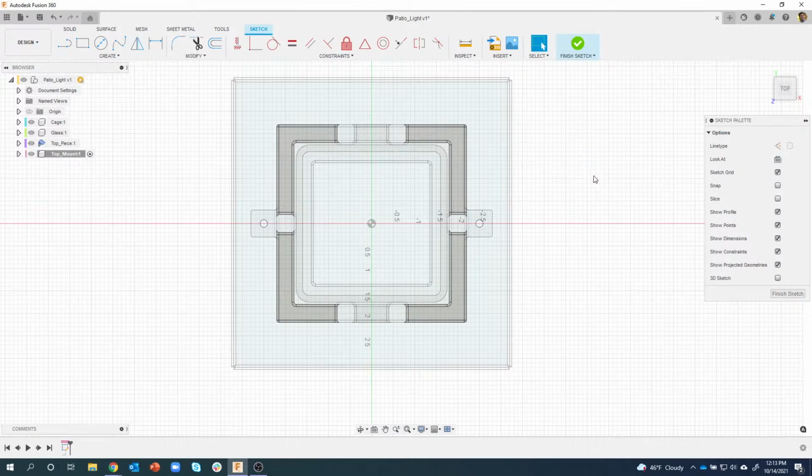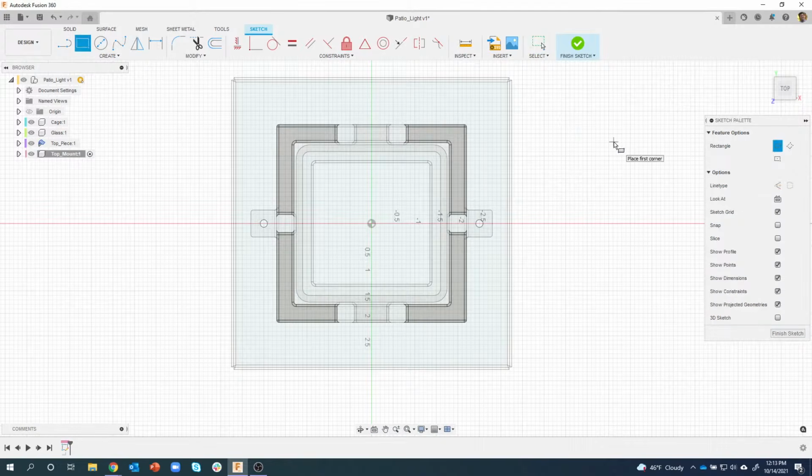So you could use R as the shortcut key, or, as you get better at it, you can remember that down and to the 2 o'clock is rectangle. Okay, so I'll go ahead and draw another centered rectangle, and just like I did before, I'm going to say 0.8, and I'm going to change this a little bit so it's more obvious.